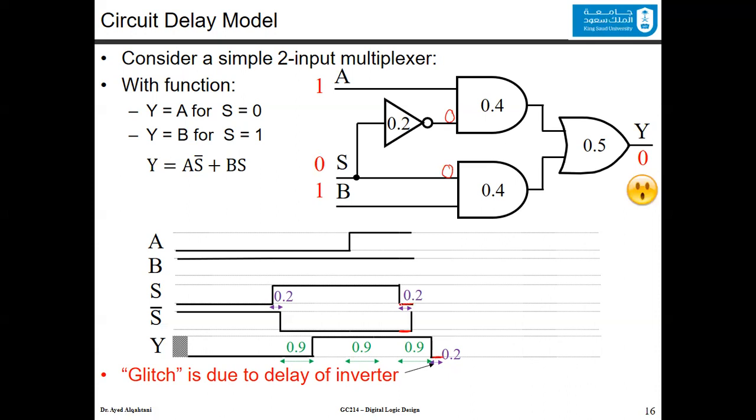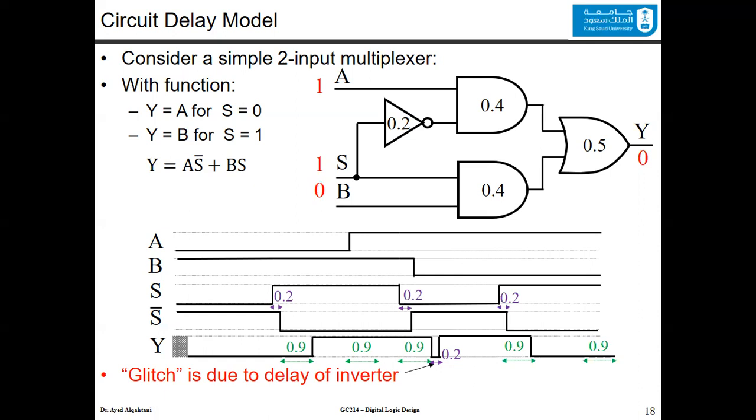Only after you pass this window, the effect will change, and you can see at that time that if you keep S the same, and you make a change in another input, let's say B, at that time the selection being the value of S is equal to 0, you will have A in the output, where you will have the value of the output matching the value of A, which is equal to 1. And because of this, after this glitch, you will have the value equal to 1, which is the normal behavior of this circuit. You can change to another value. I change it to 110, and you can follow the timing diagram, and you will find that the behavior of the sequential circuit is normal.